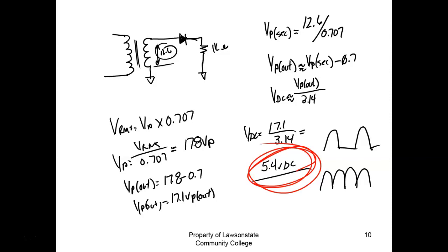Everybody in here has DC, right? What's your formula for power? Yeah, but there's one a little easier to use here. I squared R, but then we have to calculate I again. So V squared over R would be the one I would use, right? So 5.4 squared over 1,000, that's how much work we get out of it. 1K, brown, black, red.